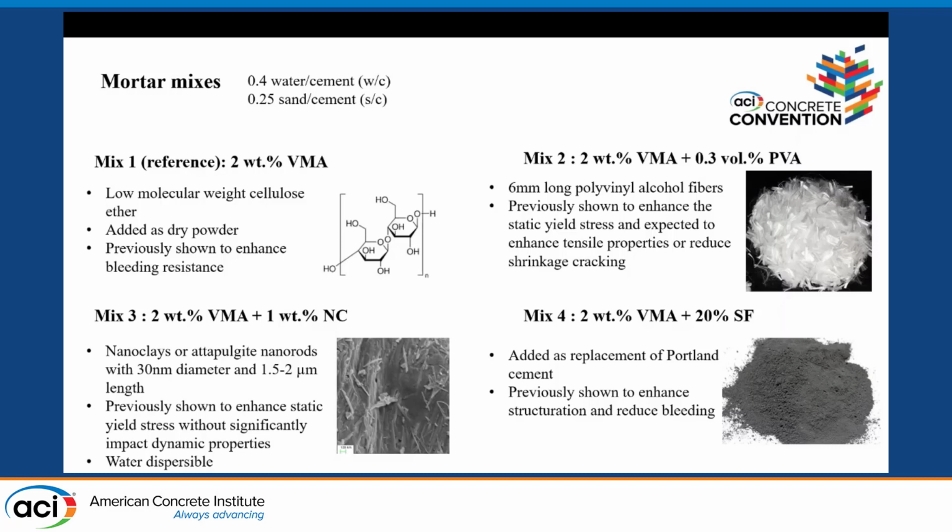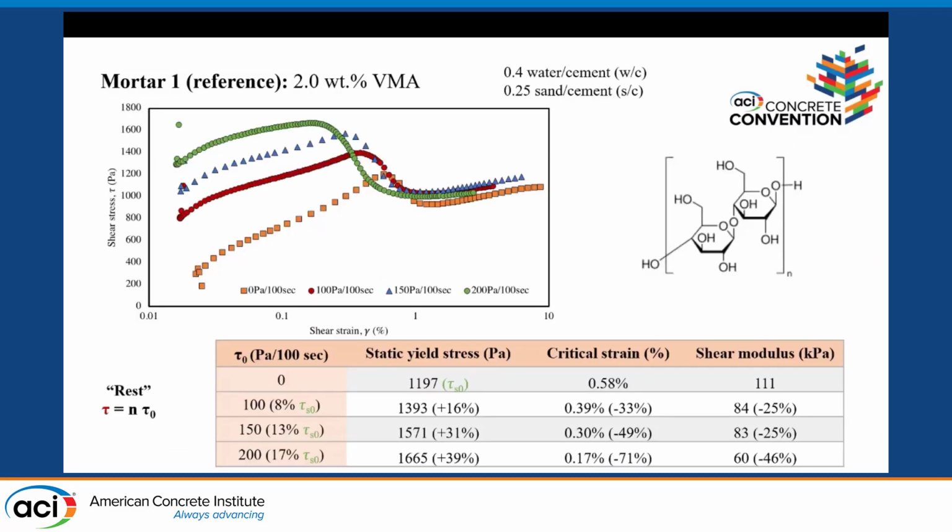And silica fume was interesting because it is also very beneficial for the rheology, just like we saw from the previous presentations. Here I just want to make sure that all the water cement ratios were fixed at 0.4, and I'm measuring mortars at a lower sand ratio. That's just because I want to be able to capture all of this with the equipment available to me. So we can look at what's happening with each of these mixtures. Rheologically, we can see that with a zero stress at rest, which is the point in orange, we can achieve somewhat of 1200 Pascal, right?